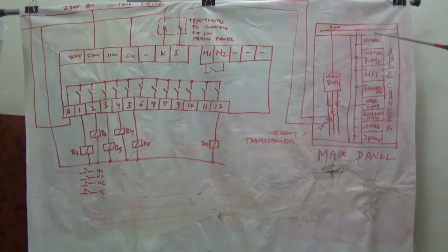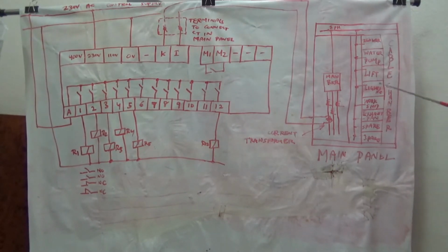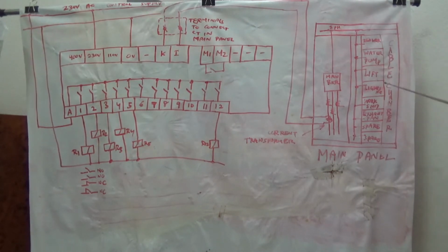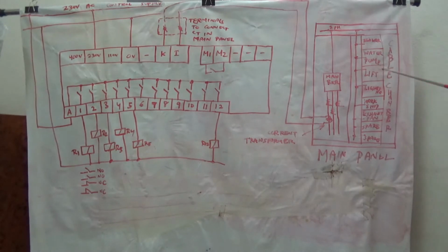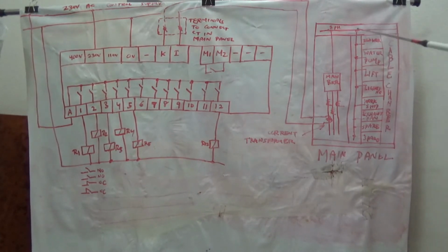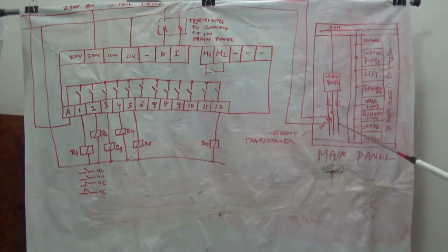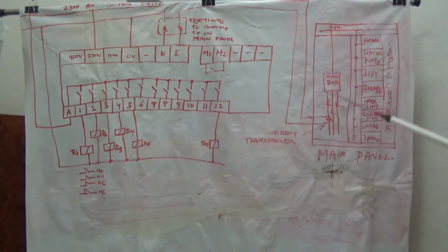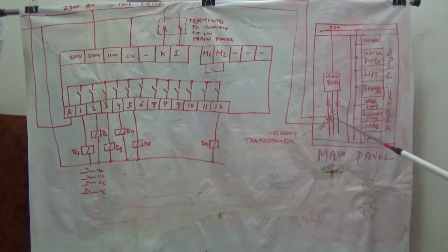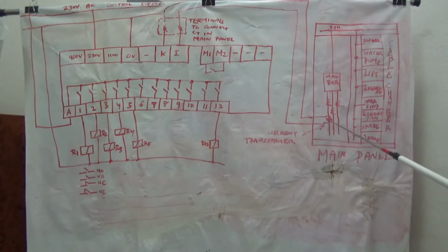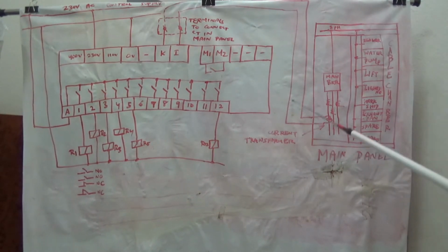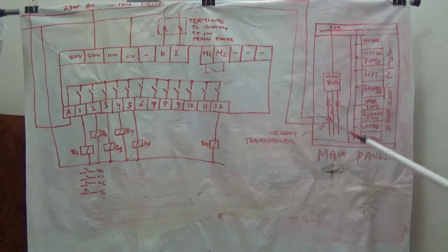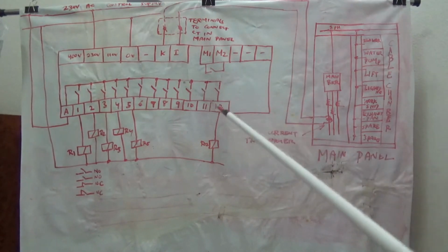So depending upon the operation of these loads, the power factor and the nature of the current is lagging because of the inductive load. These are the current transformers for metering of this panel, but there will be one more, a fourth CT, current transformer. This will feed to these points K and I.